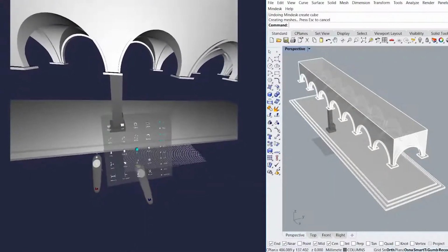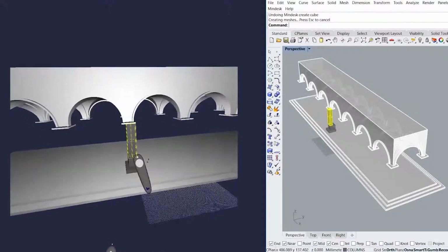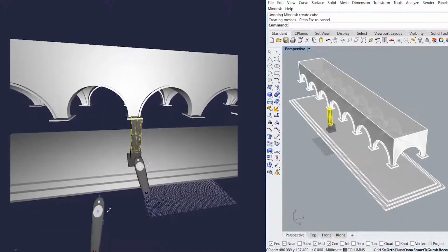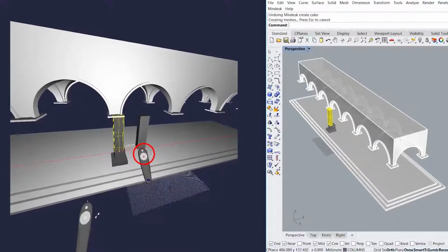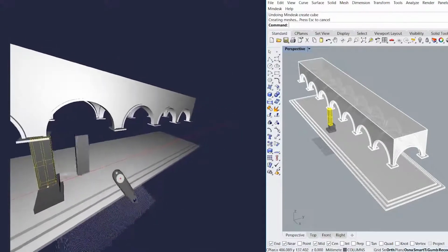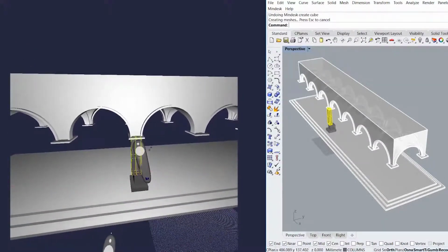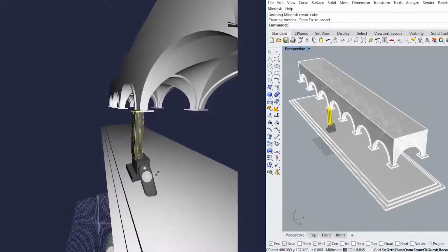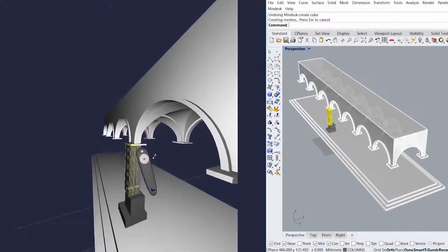So what I want to do is select the move command, grab the box, and begin by locking the red axis. So once I start moving it, if I press the thumb pad, it locks that axis, shown by a red circle on the right thumb pad, which allows me to wave it back and forth loosely, knowing that it's still on the red axis. So using the snappy draggy feature, I'm going to align it with the middle of the column. Again, I'll do it on the green axis, and I'll snap it to the center.